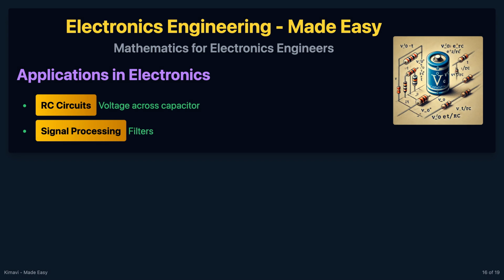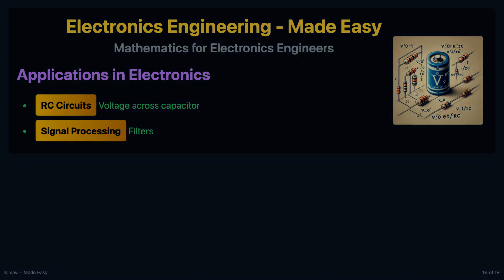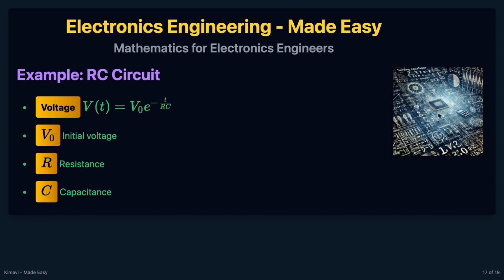Calculus has various applications in electronics. For example, in RC circuits, the voltage across a capacitor can be found using integration. In signal processing, differentiation and integration are used in analyzing and designing filters. In an RC circuit, the voltage across the capacitor is given by the equation V(t) = V0 e^(-t/RC), where V0 is the initial voltage, R is the resistance, and C is the capacitance.